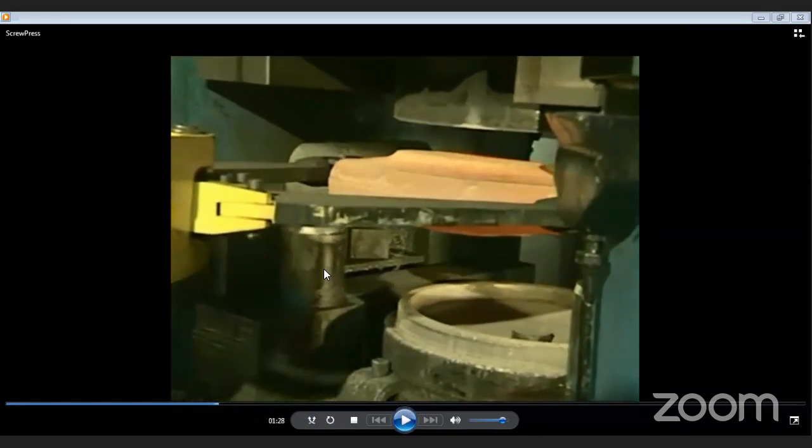Can you see this cylindrical part coming out here in the die? Yesterday we talked about parallelism between two guide pillars, right? If anyone remembers, yesterday or the day before yesterday, we talked about parallelism between two cylindrical components, guide pillars, in press tools or in plastic molds. So here again we can see these guide pillars. One more guide pillar is here on each side. The use of this guide pillar is again alignment.